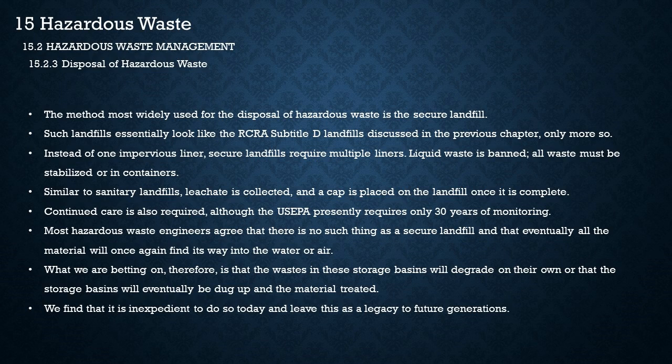Such landfills essentially look like the RCRA Subtitle D landfills discussed in the previous chapter, only more so. Instead of one impervious liner, secure landfills require multiple liners. Liquid waste is banned. All waste must be stabilized or in containers. Similar to sanitary landfills, leachate is collected and a cap is placed on the landfill once it is complete. Continued care is also required, although the U.S. EPA presently requires only 30 years of monitoring.